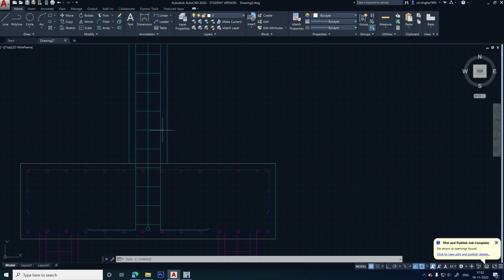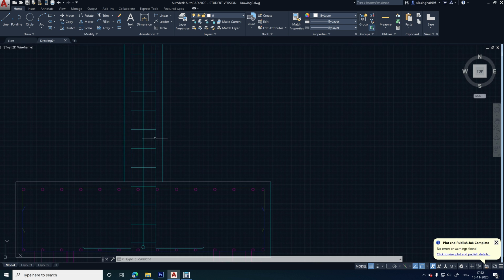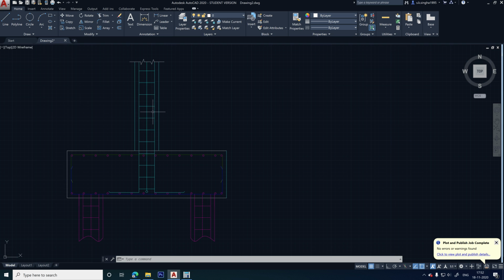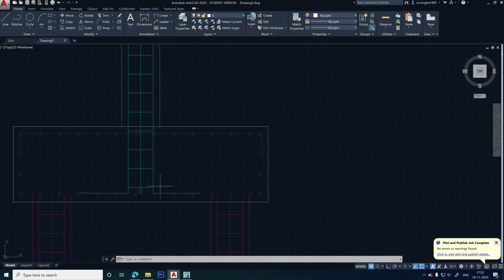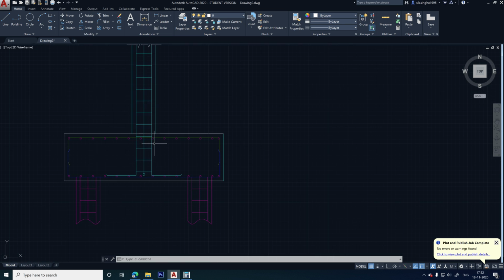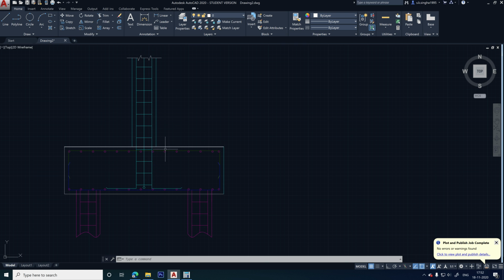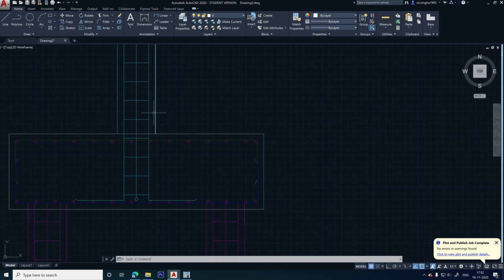Okay, up to a certain distance, the base we provide the starter bars. Directly the bars are not a very long thing. That means definitely you know that bar is having 39 feet. So definitely if there is a G+5 building or G+6 building, it will not be a single bar. So we need to add some multiple bars, right? So in the base over the pile cap where the column is located, initially we need to provide the starter bars which have a particular distance.